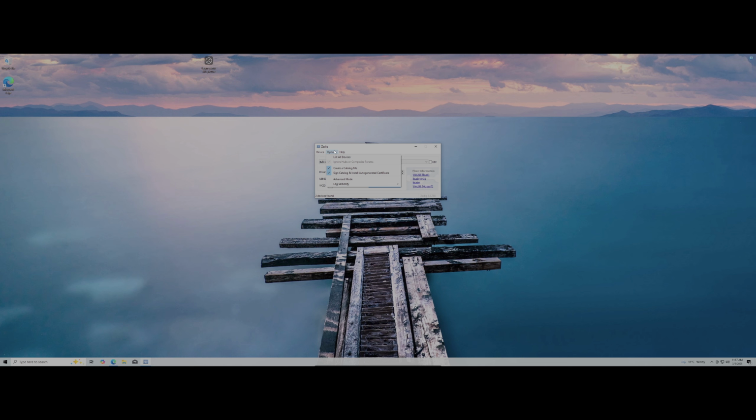The official tutorial tells you to go to options and list all devices. And then you've got a few devices here. Choose the bulk-in interface 0. That's the one that it is for me. It might be different for you. The quick start guide on RTL-SDR has a bit more information. But we'll select our interface 0. Make sure this one's set to WinUSB, and then we should just be able to install driver.